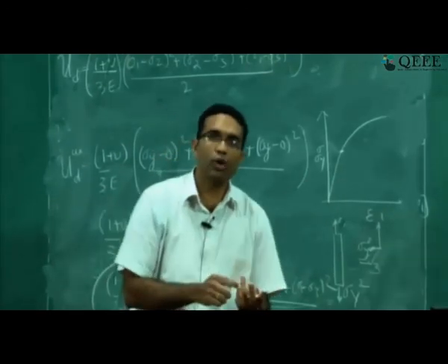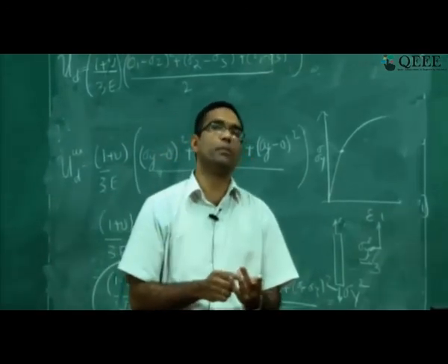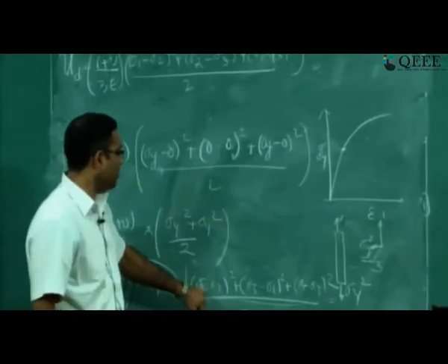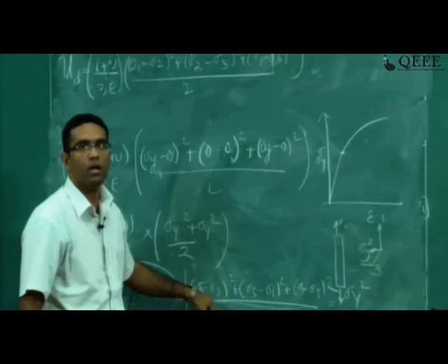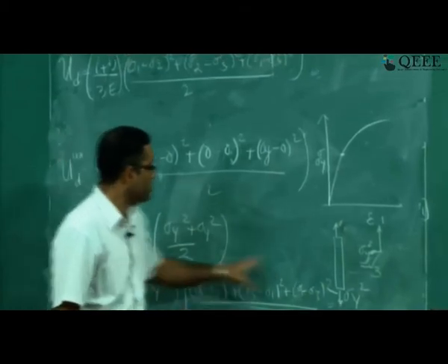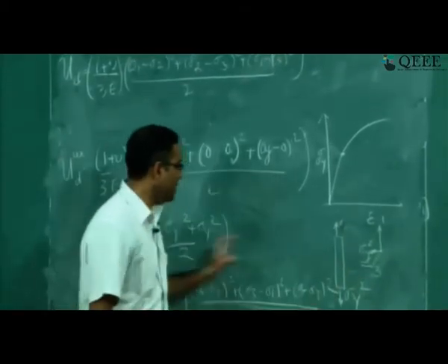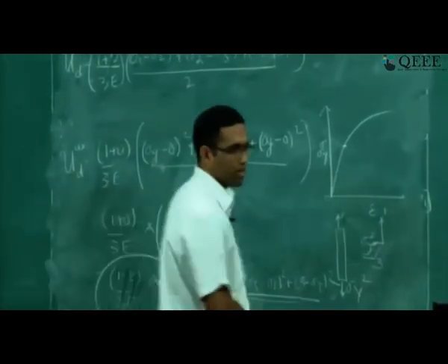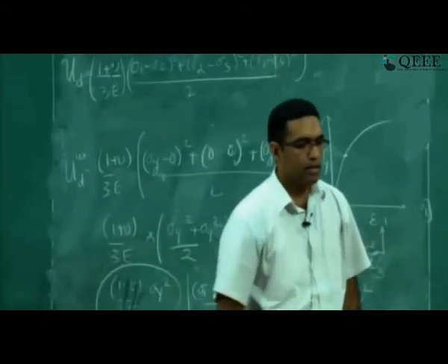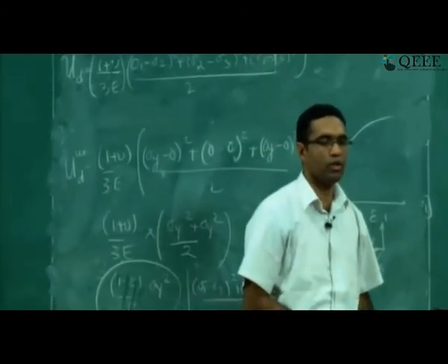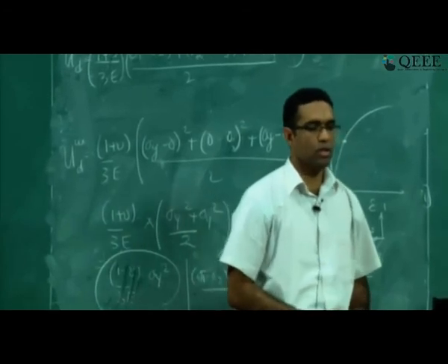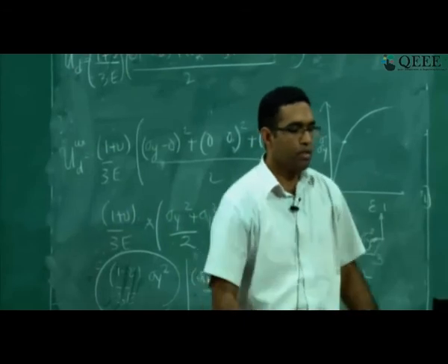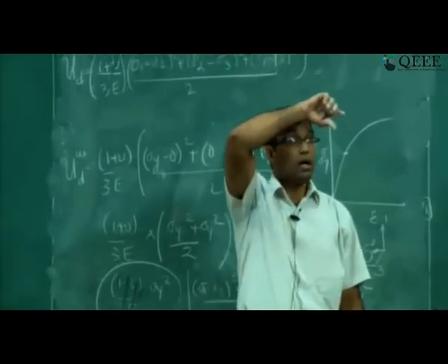They depend on the amount of load that you have supplied and on the geometry of the material. So this criterion will tell you the right combination of geometry and loading for which this can be made less than this so that the material does not yield. So this is the von Mises yield criterion, and is shown more clearly in equation number 34. This is a very important criterion for ductile materials, so please make note of it.